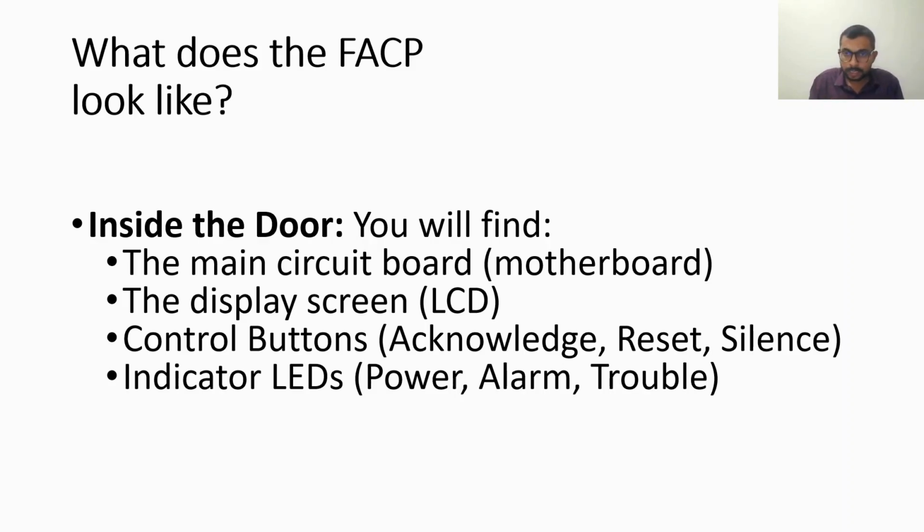Then you have the display screen, the LCD screen. Then you have the control buttons, which normally comprise acknowledge, reset, and silence. Then we have the indicator LEDs, which are the power LED, alarm, trouble, just to name a few. So these are typically the components which are present in the fire alarm control panel.